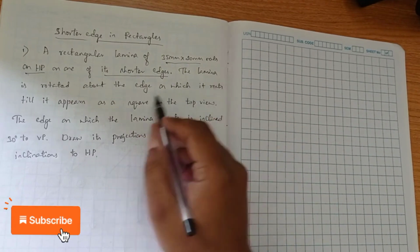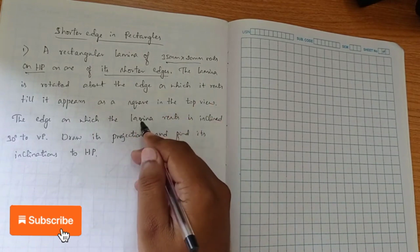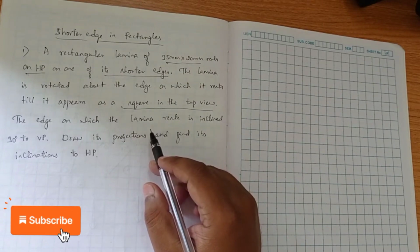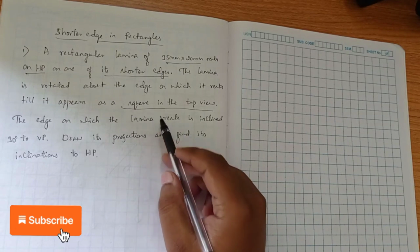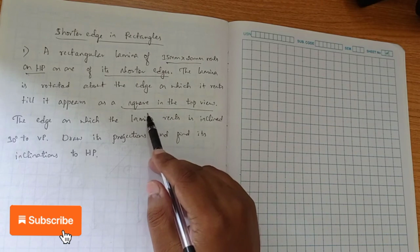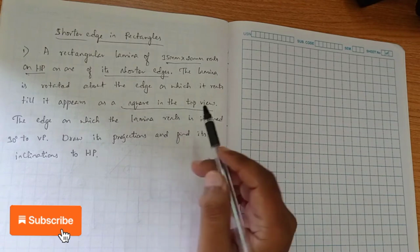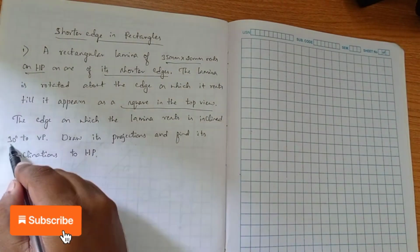Now the lamina is rotated about the edge on which it rests till it appears as a square in the top view. So it is similar to your isosceles triangular problem, wherein the second position is an equilateral triangle, right? Similar to it, here they have not mentioned the angle of inclination to HP. Instead of that, they have mentioned a second position top view. In the second position top view, we get a square of dimension 20. Now the edge on which the lamina rests is inclined to VP at 30 degrees.